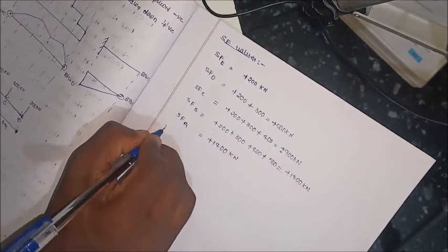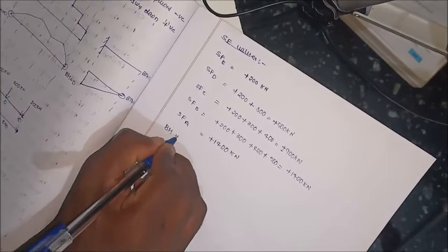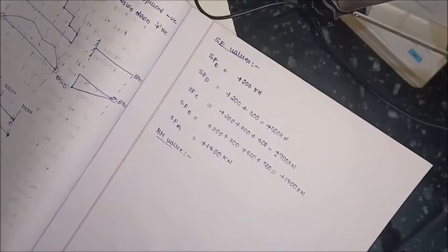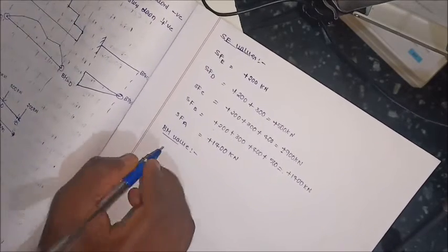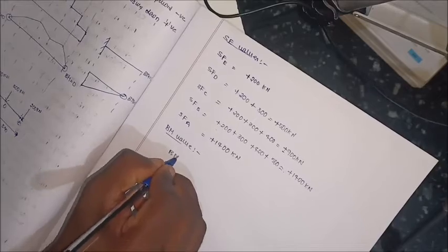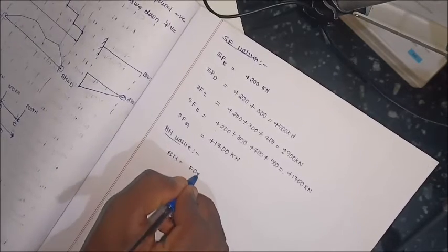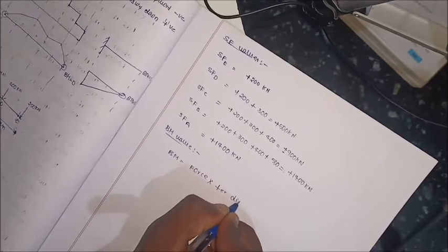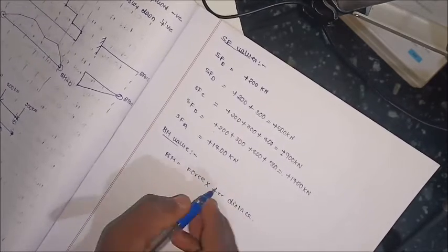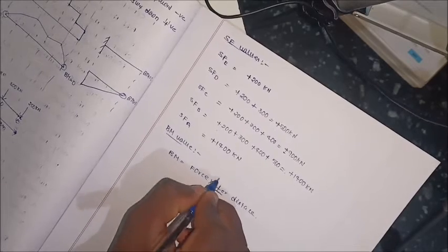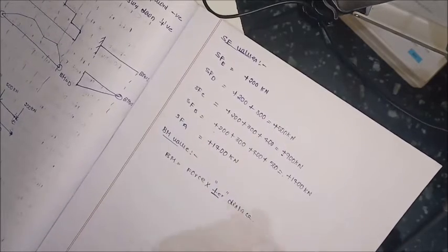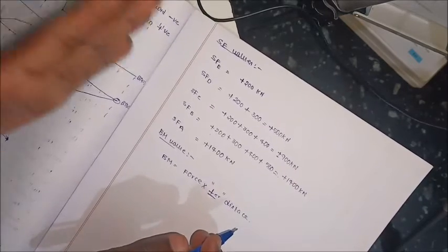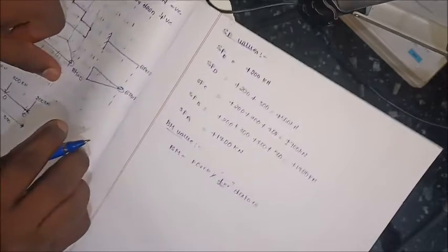In the same way, calculate the bending moment values. The bending moment is force into perpendicular distance. This perpendicular distance is important, not any other distances. Consider the perpendicular distance between the force and the considered point.